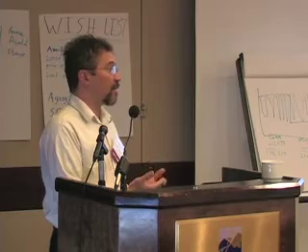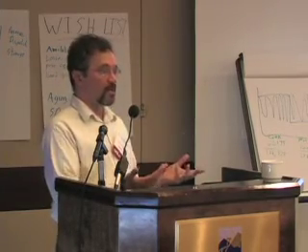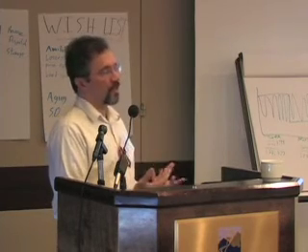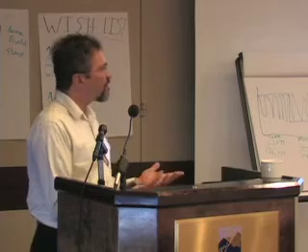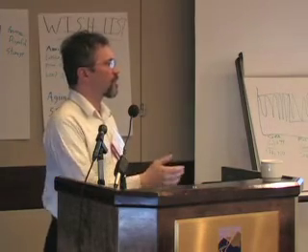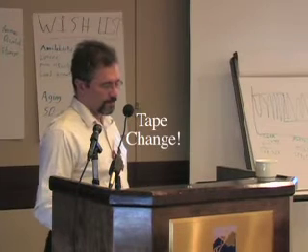Now, lead-acid batteries need to be brought up to 100% every once in a while to equalize the cells. But doing it on a regular basis is just sort of inefficient. So our default's 80%, which over time we've found is often the best answer, but it's worth doing a sensitivity on Homer.